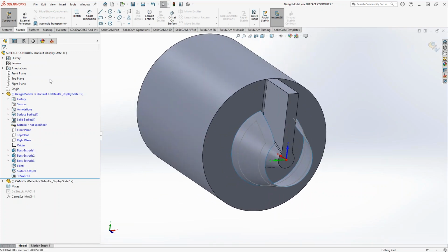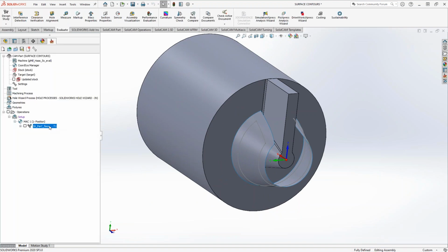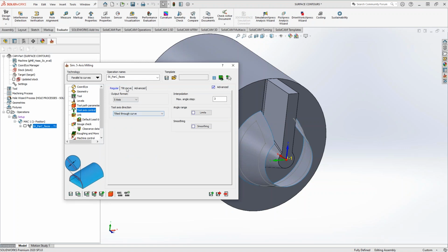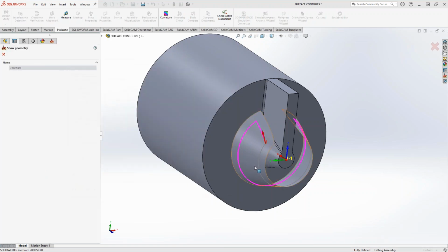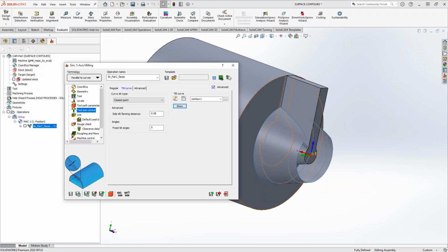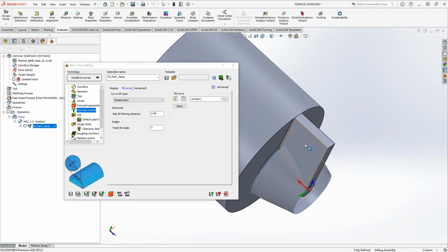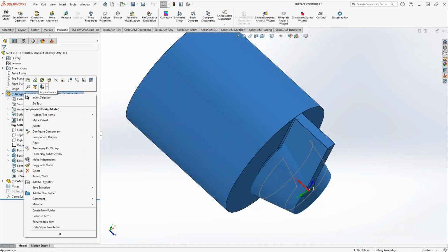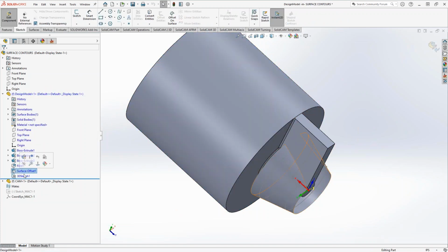And the reason I did that is because if we go back into the part, and again, this is more for 5-axis, but you can definitely create this geometry with this technique I'm about to show you. I did this as a tilted through curve, and the curve that I chose is the one that I created there, because I just grabbed that edge and went around. Because I'm telling the tool to pass through those curves, I've angled it away from those walls. So the SolidWorks functionality that we use to do that is this. Let's go in here and I'm going to recreate it so you guys can see how we did that. Let's hide that